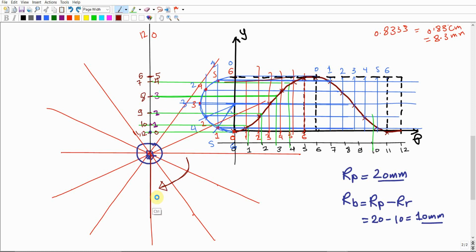this course. If the direction of the cam rotation is not given, assume that it rotates in the clockwise direction, and in this case you're going to do the numbering in the counterclockwise direction. Make sense? Counterclockwise direction means that this is going to be 0, this is going to be 1 and 2 and so on. So this is 0. Then we're going to have line number 1. This is line 2, line 3, and line 4, and line 5, 6, 7, 8, and 9, 10, which should be this line, and 11, and we return back again to 12.